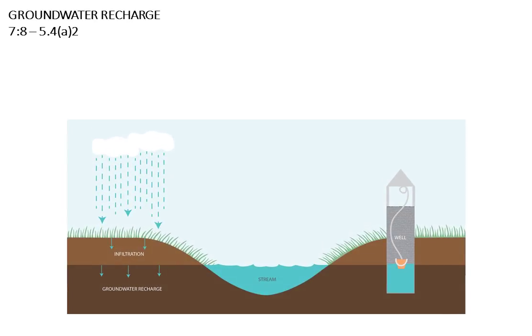The second design and performance standard is the groundwater recharge standard. When stormwater lands on or flows over pervious areas, some of it infiltrates into the soil. Some of the runoff that infiltrates will be removed by vegetation through the process of evapotranspiration. The runoff that infiltrates below the root zone of the vegetation enters the groundwater table. Recharging groundwater is very important for maintaining base flow into streams and other water bodies. A lack of groundwater recharge as a result of development can lead to increased flooding during wet weather and decreased surface water levels during dry weather.